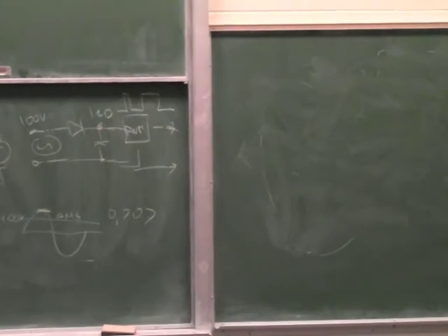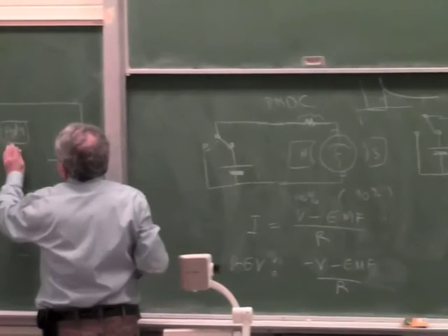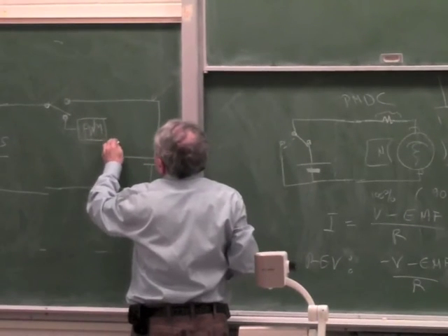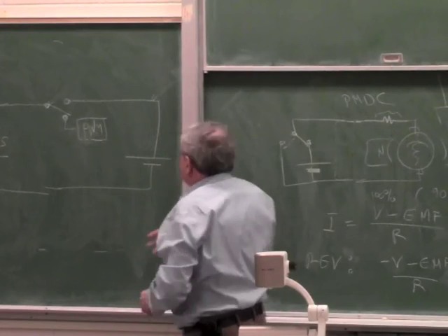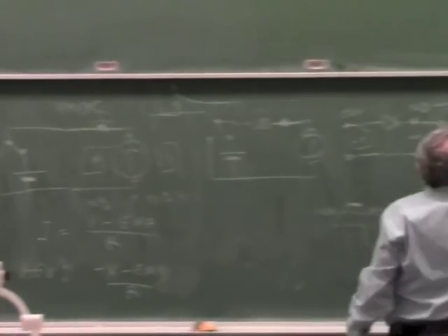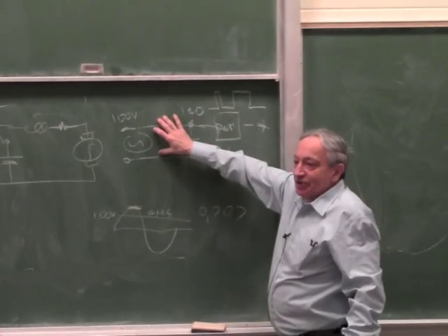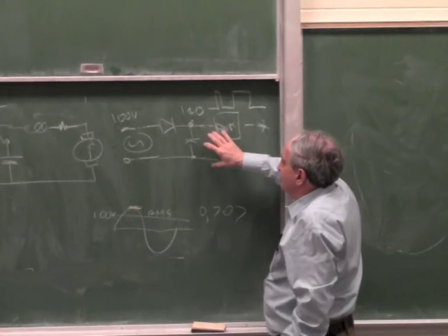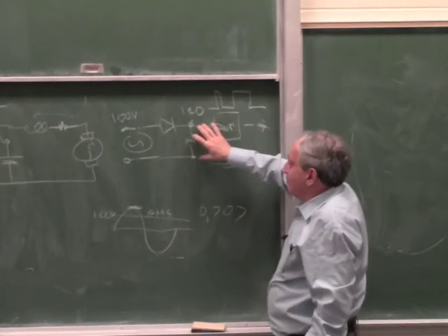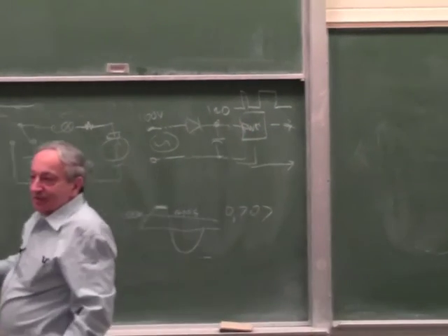Inside you usually use a transformer to boost the voltage, because sometimes this voltage has to be higher than this voltage. So what you do is you chop it first to high frequency AC, goes through a transformer. So sometimes there's another stage here.